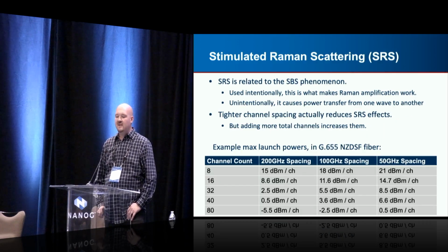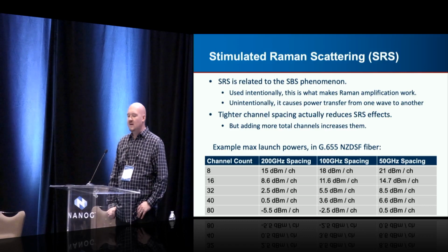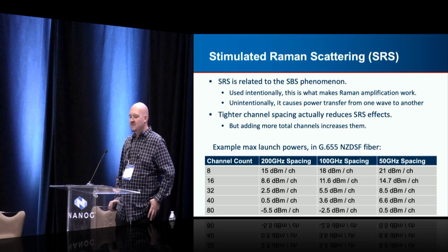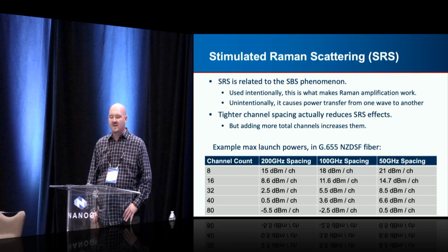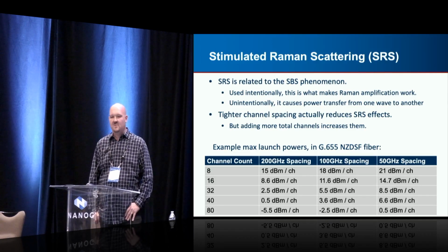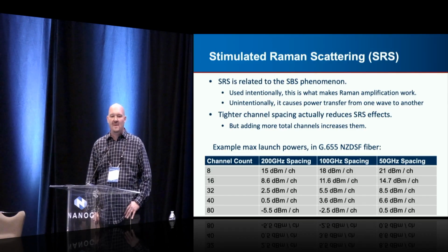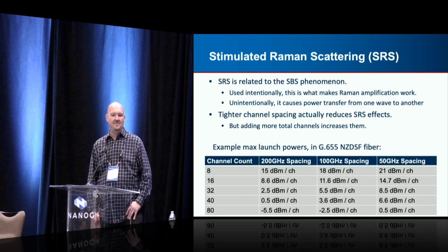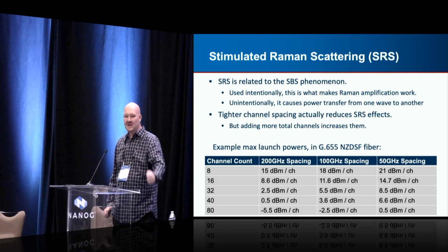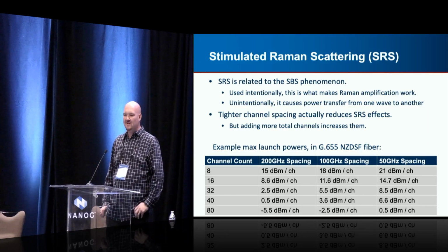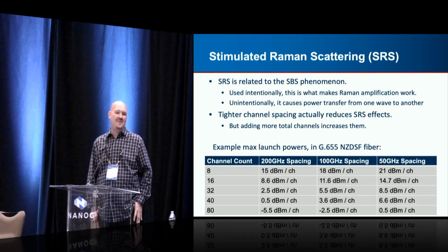SRS, stimulated Raman scattering, is how Raman amplification works. What's happening here is you're transferring power from one wavelength to another. Like I said, when you do that intentionally, when you transfer power from a pump laser that you don't care about into a signal that you do care about, it's amplification and it's good. When this happens between two of your signals that you do care about and you don't want it to, it's bad.